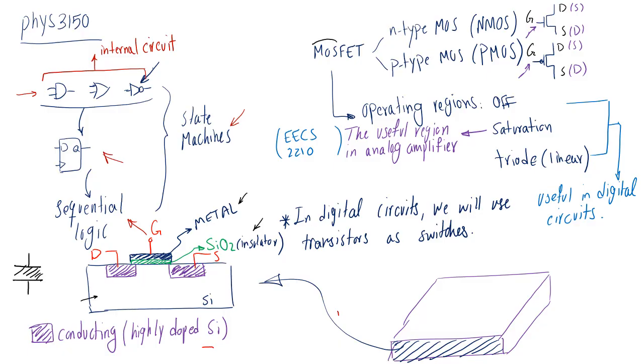So I'm connecting this to my gate, and then the body of the silicon is, let's say, connected to ground. By the way, this body is the fourth terminal that I was talking about. So sometimes in the symbol, they show something like this and they call it body or substrate. Okay, so that's the fourth terminal that we're not going to be talking about, because most of the time for NMOS transistors, it is connected to ground, and for the PMOS transistors, it is connected to VDD.